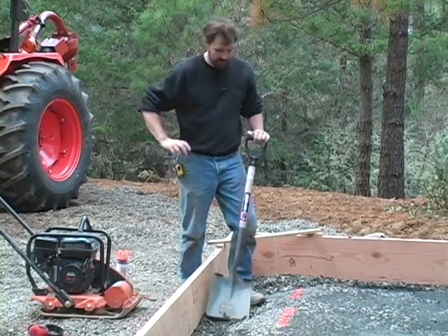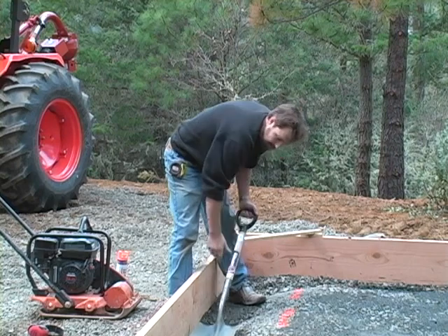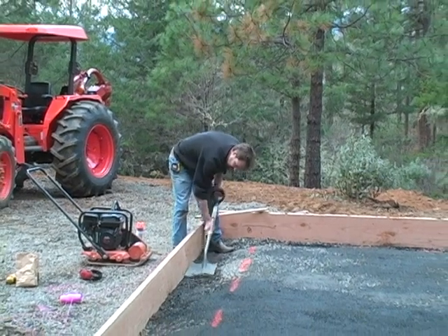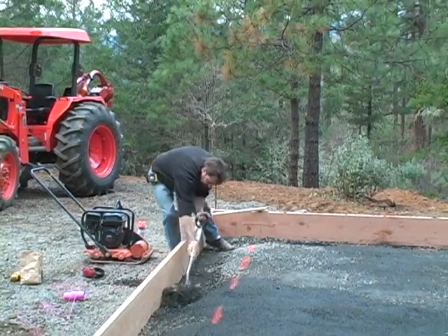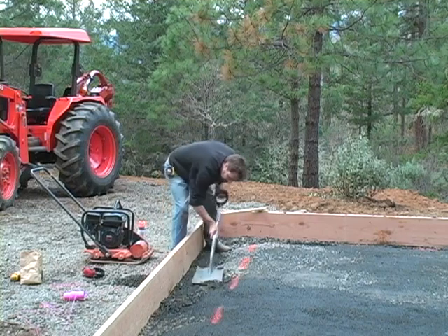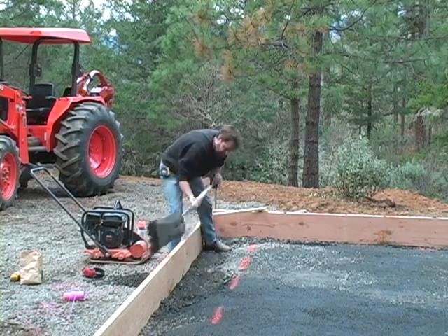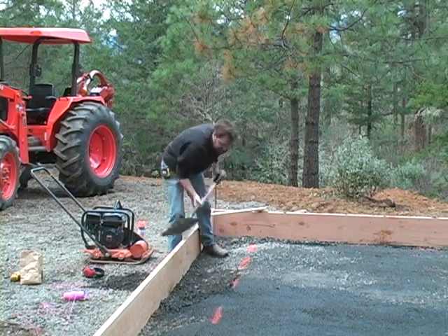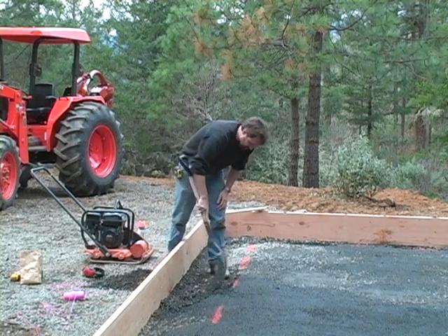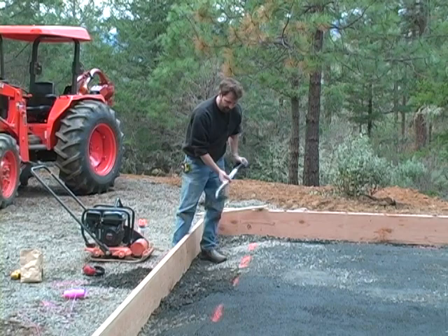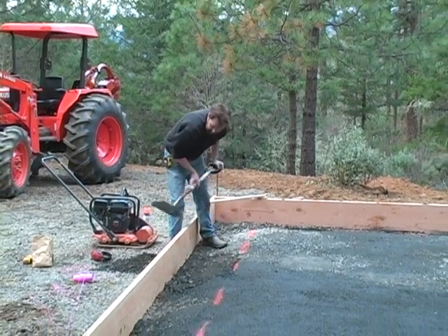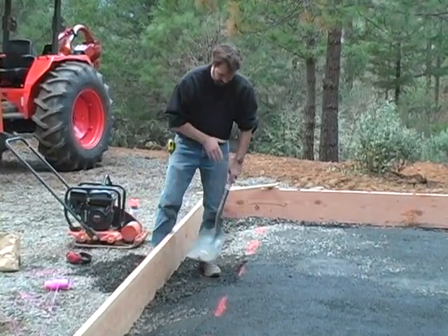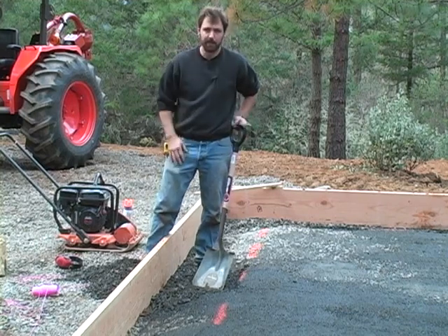So using a flat blade shovel, I'll just cut out right along that line that we've marked. And I want to be sure to keep my shovel as flat as possible so that I'm coming out level from the bottom of my footing across here. So I start at the outside and create a level area, and then move over from there and follow that area over to the line. And you can see it holds up pretty well because of the compaction. It will slough off a little. It's not a big deal at this point. It's the difference between compacted rock and concrete. So you want to be sure to have a footing that's wide enough, and at the same time, you don't want to worry about this stuff that falls in. We're going to run the compactor through here one more time to compact the bottom of this footing before we're all done.